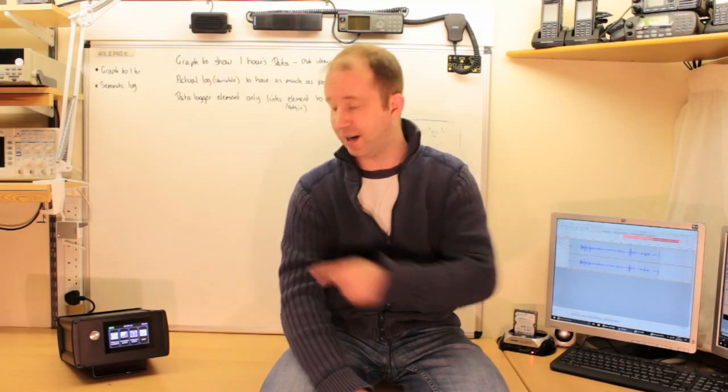On later implementations, one of the things that I'd like to do is speed control, so that you could set a target air pressure and this device would control the speed of your air movement system, so that it neither drew too little nor too much air and thus exposed the enclosure to too little or too much vacuum, because those 2 conditions in their extreme can be dangerous.